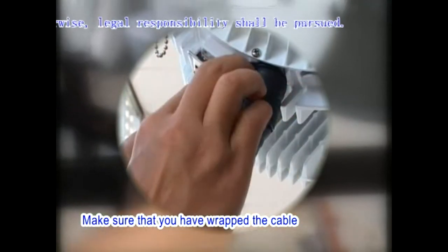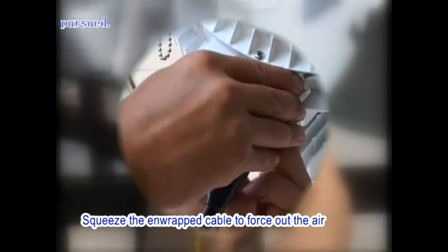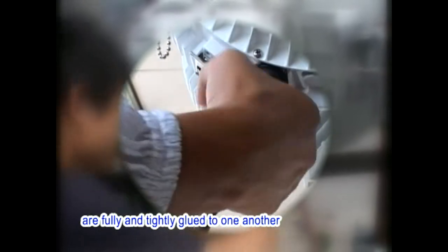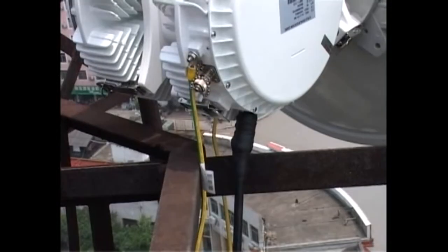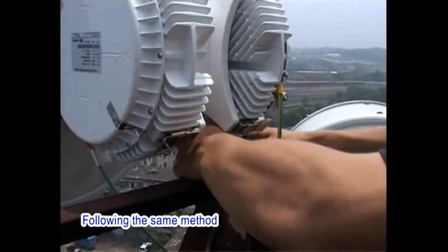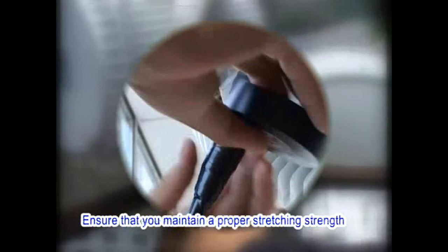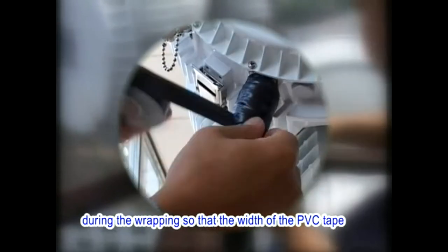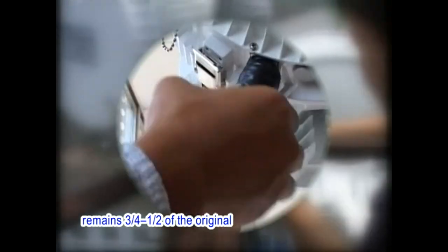Make sure that you have wrapped the cable with 3 layers of waterproof tape. Squeeze the in-wrapped cable to force out the air between the layers so that the 3 layers are fully and tightly glued to one another. Following the same method, wrap 3 layers of PVC tape around the in-wrapped cable. Ensure that you maintain a proper stretching strength during the wrapping so that the width of the PVC tape remains 3/4 to half of the original.